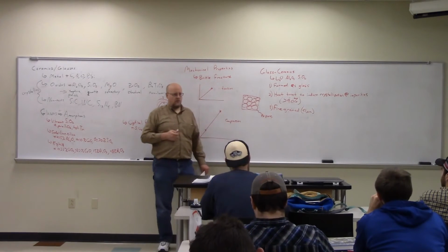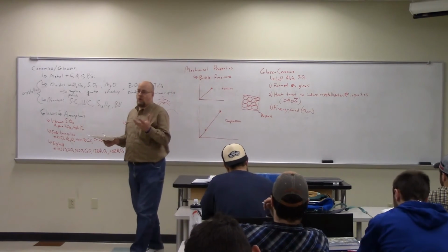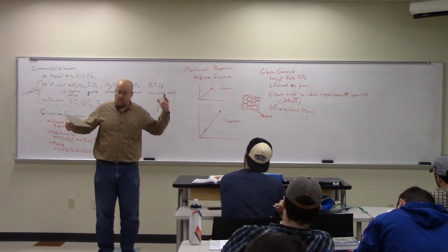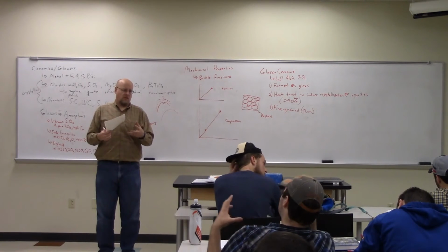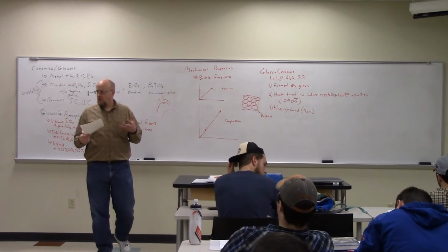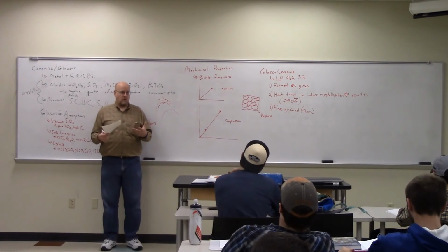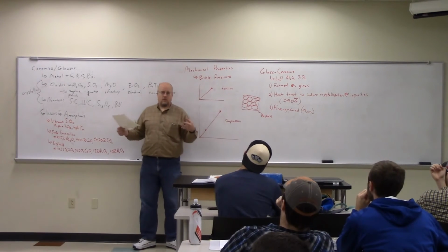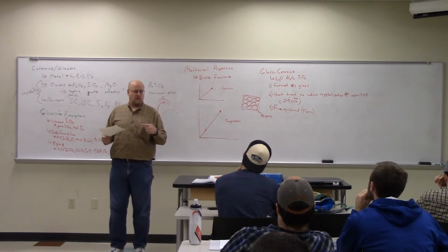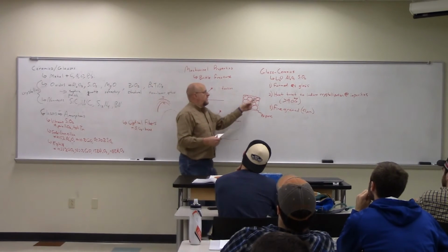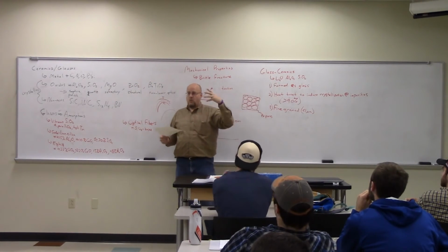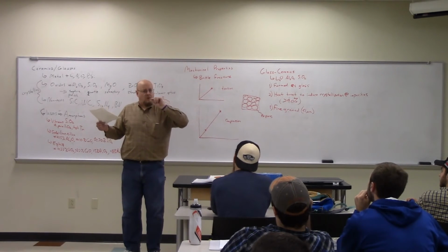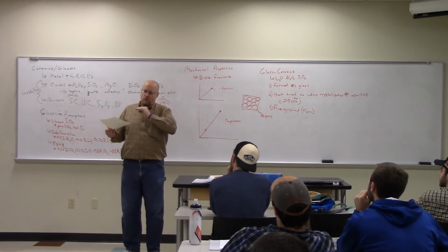Like the grain boundary areas, which, if we took a crystalline material and tried to make it into a shape, we'd have to compact the crystals together at high temperature and pressure in order to get them to form a solid chunk. And inevitably in doing so, we're going to have porosity at the grain boundaries because we're never going to get them to squish together and fill in all the spaces. However, if we start out with something that's amorphous to begin with, it's essentially a liquid, and so it's able to flow, fill all the spaces, and then I grow grains from within it so that there's no porosity in the material.